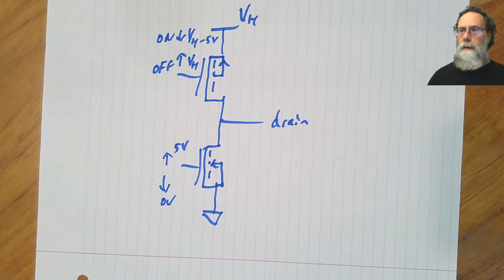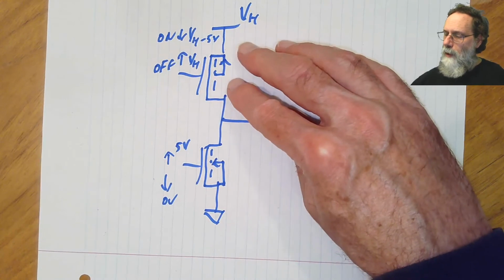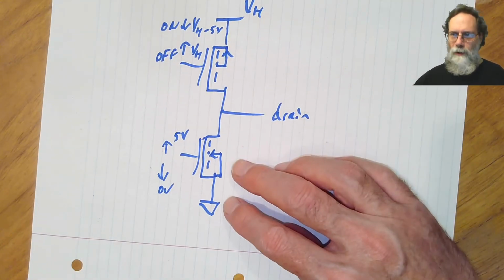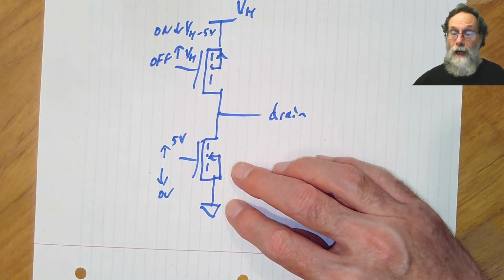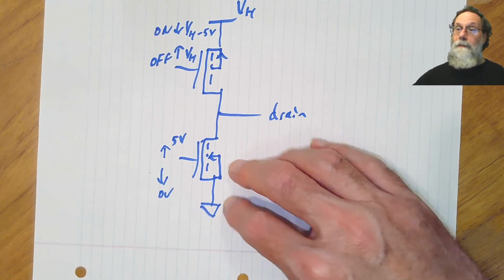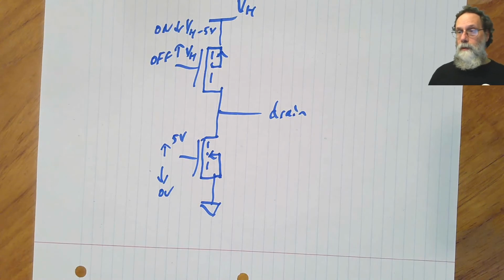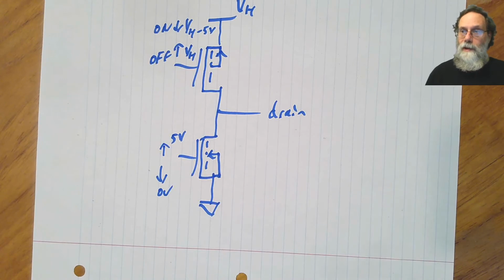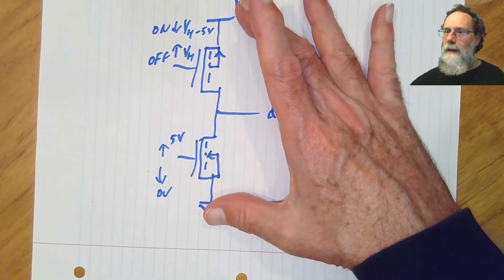But we've got a problem, because the signaling levels we want here are 4 volts and 9 volts now, and down here we want 0 volts and 5 volts. And those are not the same anymore. Furthermore, if we try to use the trick of an inverter as a digital amplifier for driving this gate fast, this one's no problem. We can drive this one because 0 and 5 volts are exactly the sorts of voltage we use for those inverters. But 4 volts and 9 volts are not. And we don't have a 4-volt supply sitting around. We've just got the 0 and 9 here.